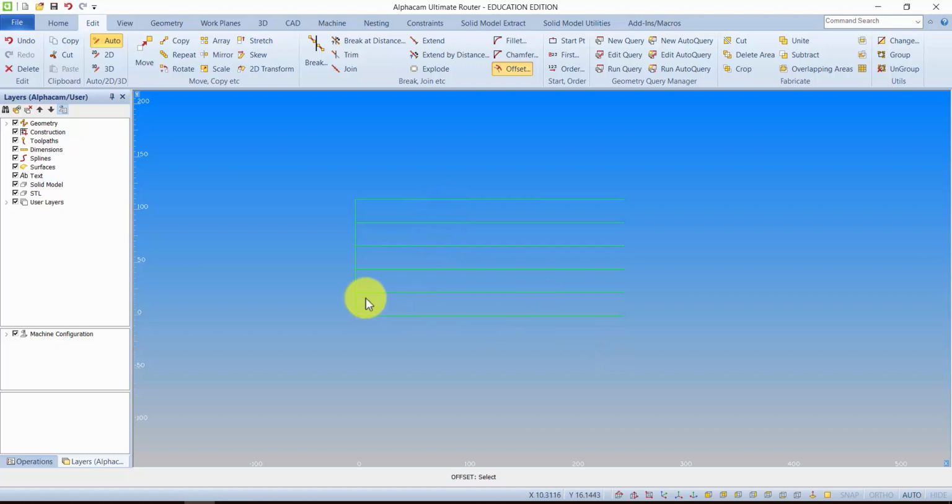Okay, and let's now put the first line up, which goes up at 60 degrees using the same method as previously. So click Rotate, click that bottom line and press Finish. The base point is going to be the point of rotation, so select that point there, and the angle is going to be 60 degrees. So simply type in 60 and press Enter, and then specify the number you wish. So I want 2, I want to leave the original, so 2, enter.